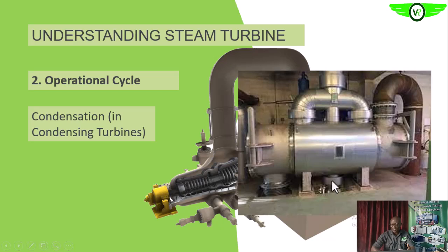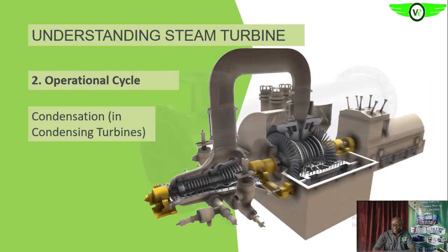There's usually a condensate pump that will take the water from the hot well into the condensate line back to your deaerator, okay. So the cooling water, having gained heat from this heat exchanger, is discharged through this line. Are we getting it? Back to your cooling tower, okay. So this is the condensate line.